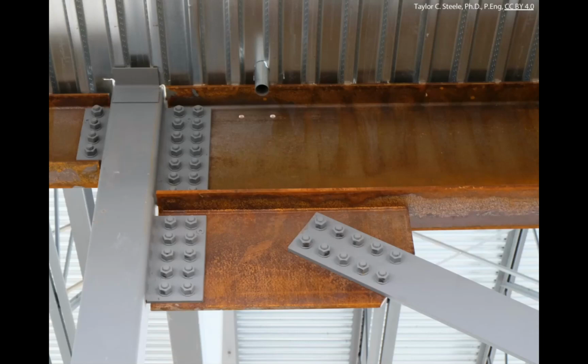So this is the brace down here that's coming in. That's the brace, and it goes down, of course, all the way down somewhere. And it gets connected into the beam and column interface through the gusset plate, right? This big plate here is the gusset plate. The gusset is connected to the column with a plate as well. The beam's connected to the column with a plate. When we're doing our structural analysis, this is our joint, right? So that's our joint there.